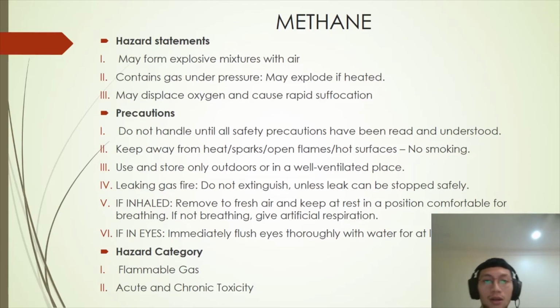Okay, the precaution of methane. Firstly, we do not handle until all safety precautions have been read and understood. Second, you have to use and store only outdoors or in a well ventilated place. You have to keep away from heat, sparks, open flames, hot surface, and especially no smoking near it. If there is a leaking gas fire, do not extinguish unless leak can be stopped safely. Besides that, we need to use a backflow preventative device in the piping and eliminate all ignition sources if safe to do so. Lastly, use only with equipment rated for cylinder pressure.